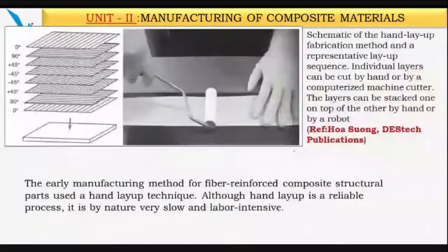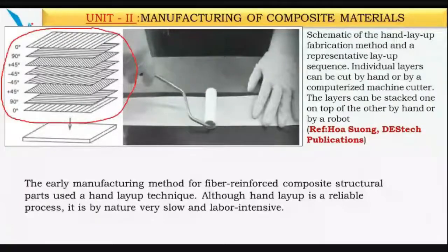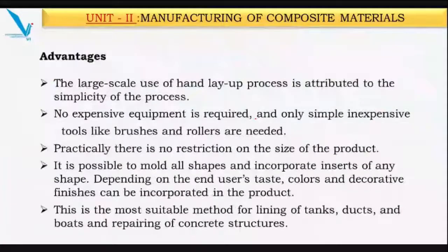Here you can go for alternate layers with different fiber orientations, and that is also possible with the hand-layup method. So to get a tailored design, this fiber orientation or stacking sequence is possible with the hand-layup method also. Okay, what are the advantages? We'll just read one by one. What are the advantages of the hand-layup process and what are the drawbacks?